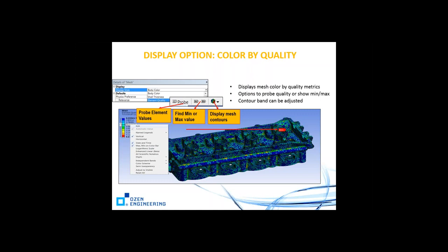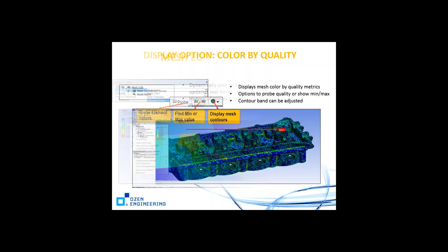And then in version 16, right after you mesh, under the mesh details, you can right away plot the element quality, and you're going to get a contour plot like this. In this contour plot, the blue elements are good. The red elements are bad. Or you can see that there are some yellows. I can't see any red here. It says the minimum is over here. But right away, right after you mesh it, you'll get a plot that looks like this in version 16.